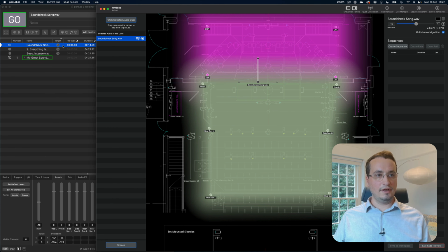So if your pros, for example, is a little bit hotter because you've got bigger, punchier speakers in your pros than your side surrounds and your rear surrounds, you need to be able to offset that level difference somewhere using some kind of gain stage. That could be on an amplifier, it could be on your QLab desk channels on the console, wherever that might be. You want to basically be able to balance out your sound system.